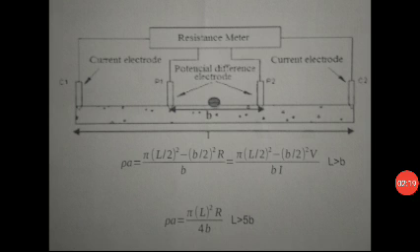Vertical electrical soundings, VES. In this method, a number of rho A values are measured at the same place by increasing the distance between the current electrodes each time after taking the reading. The successive increase in distance makes the current penetrate more and more deeply. Generally, the depth of penetration of the current is about one-third of the distance between the current electrodes.